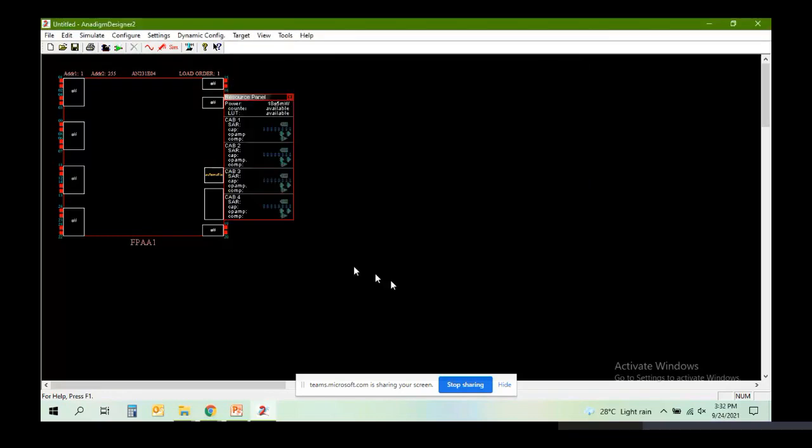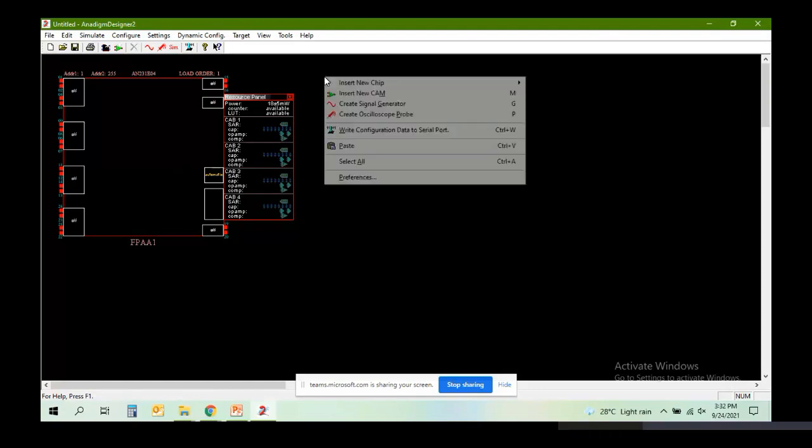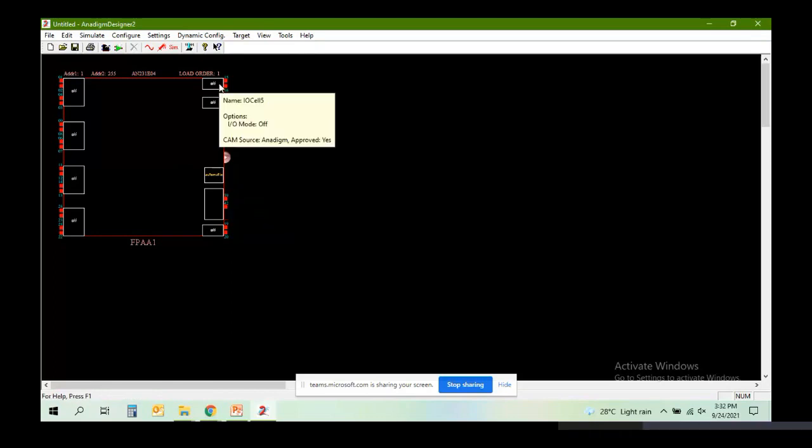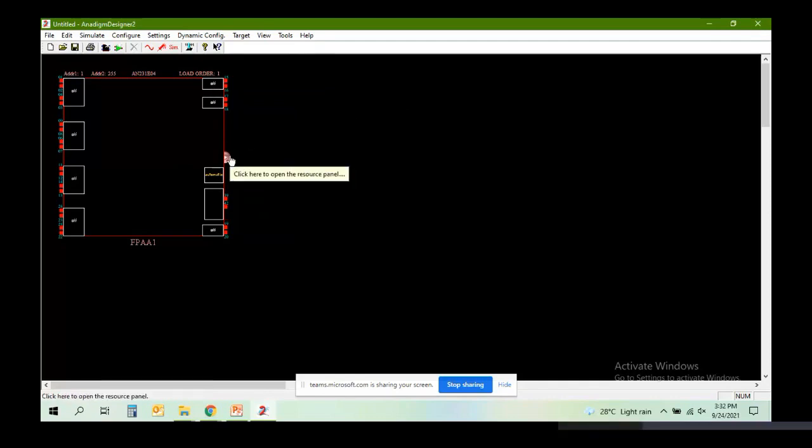And one more is the FPAA resources, CAB 0, CAB 1 to CAB 4. Whatever CAM you use inside the FPAA will take the resources of these CABs. You don't have control over the CAB resources. Once all the CAB resources are exhausted, you can't use any more functions inside the same FPAA. You have to place one more new FPAA and interconnect the two, feeding the output of this FPAA to the adjacent FPAA as an input. That way you can design complex systems.